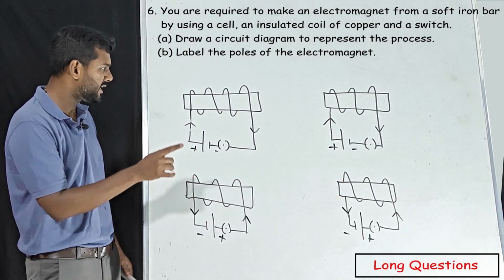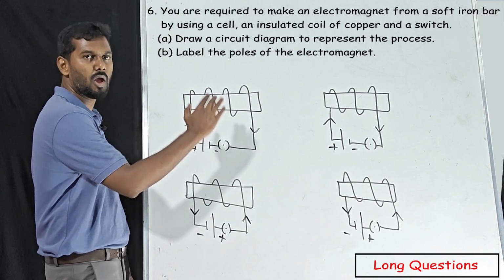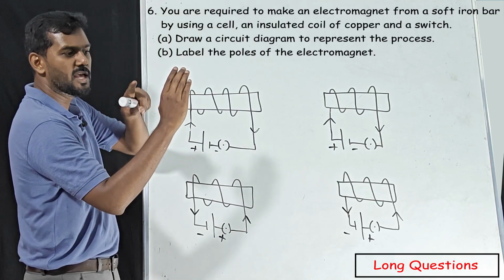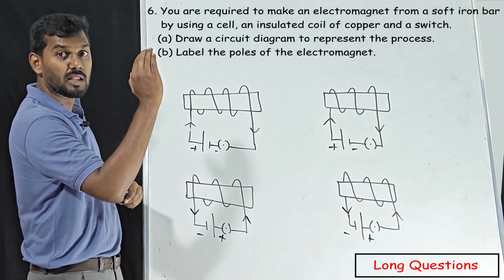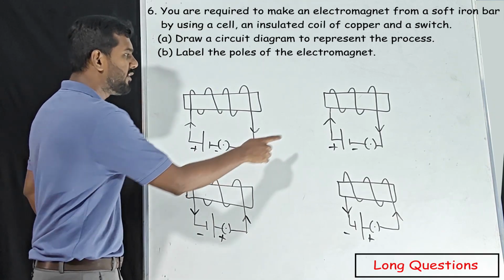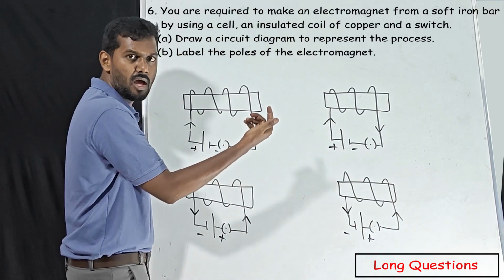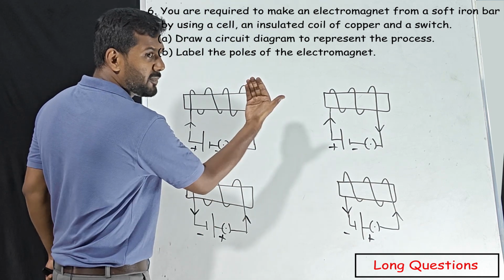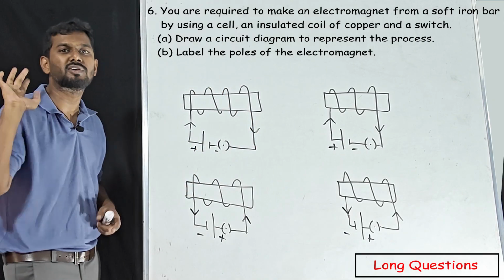Once you find that this first line is above, you have to hold it like this. If the first line is above, hold it like this. All the fingers represent the first wire, which is going above the rod. If you see a diagram where the first wire is coming from behind the bar, you have to hold it like this. This is the first step.